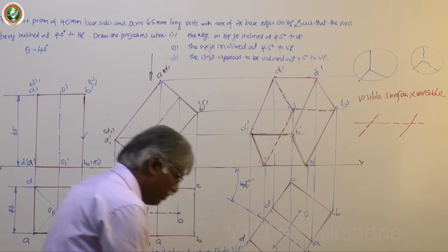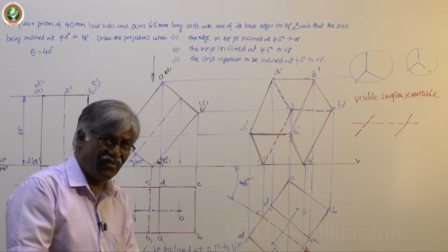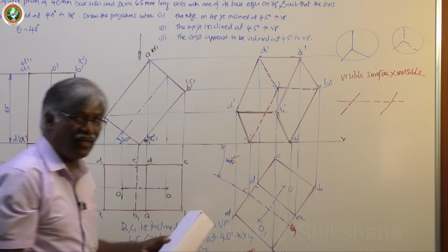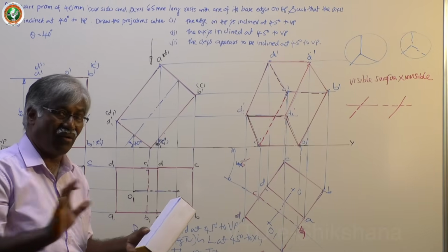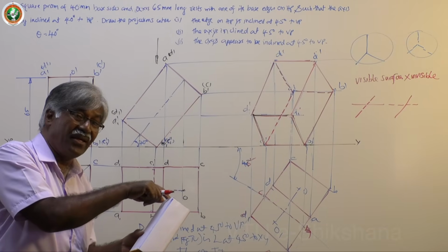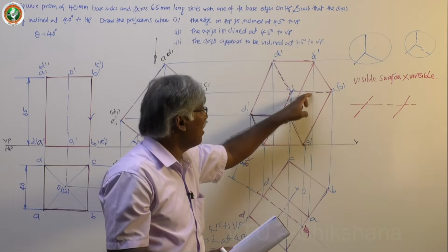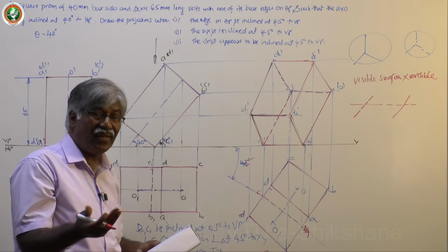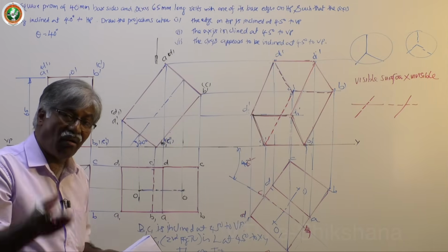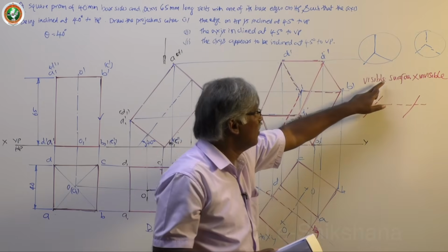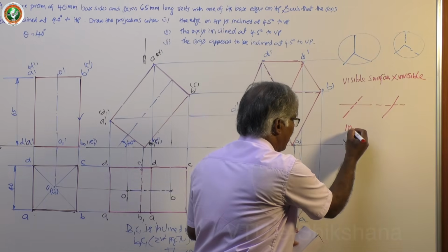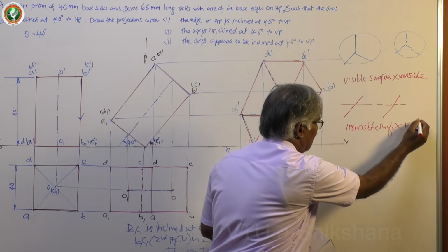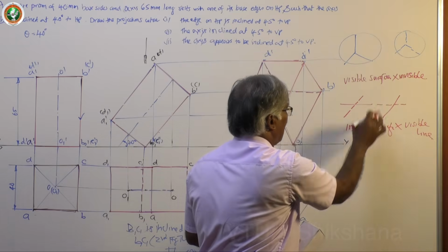Basic, I will repeat, the basic concept is visible key surface or invisible key surface. So, the visible key surface in this case is the base, I have darkened the base. Fine. Next basic procedure is all boundary lines are dark. Next, invisible key surface edges other than boundary lines are dotted. I have two lines which are not covered by the boundary line. Now, how to complete? Either through crossing line or Benz or basic reference: visible surface, invisible line; invisible surface, visible line. This is always true. This is the fundamental concept.